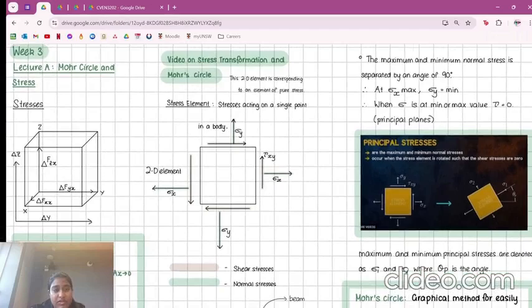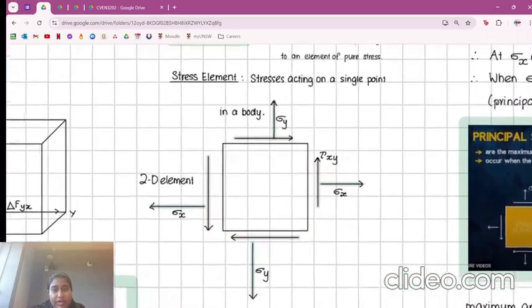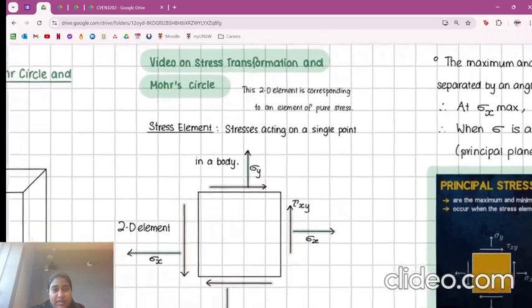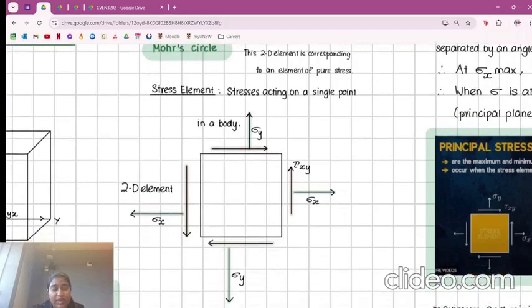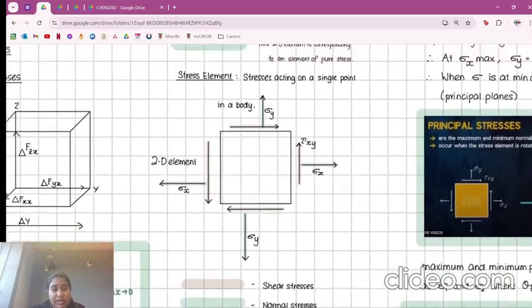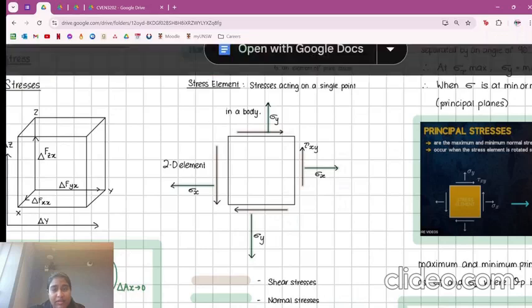I'll just zoom into my notes here, because I think this is a pretty good place to start. Imagine this diagram here is representative of a soil particle in a soil sample. At any point, there are 2 types of stress acting on that soil element, or the stress element. One of them is the shear stress and the other is the normal stress. I've highlighted them in green and brown there, so you can see where they'll be acting on the element.